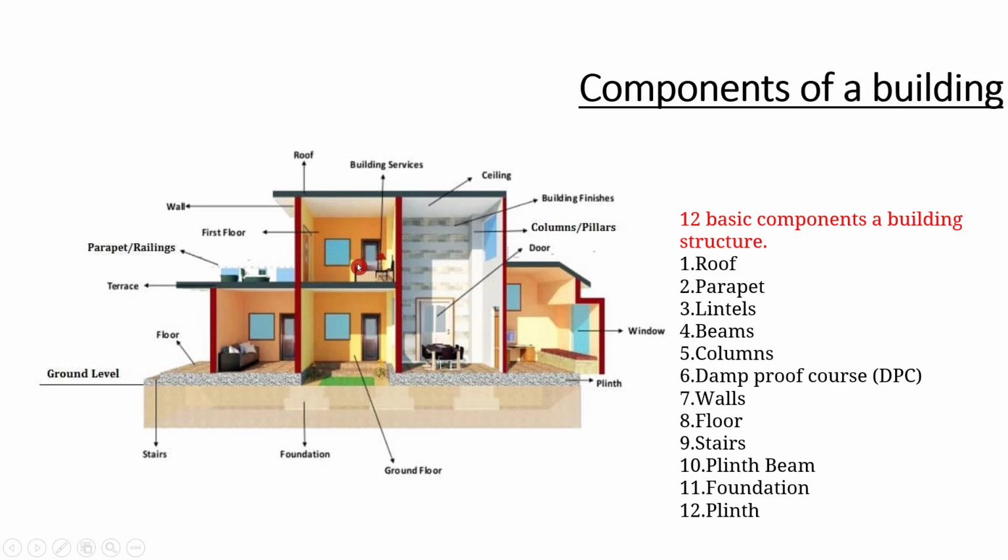You can see that for all the doors and windows the top level is almost the same, so it is almost always kept the same at the 2 meter height. And we are providing a lintel, say a lengthier beam which runs throughout the perimeter for taking the loads that are coming from above the walls. It means these loads will be transferred to the lintels, so there won't be any more stress concentration at the windows and the door portions.